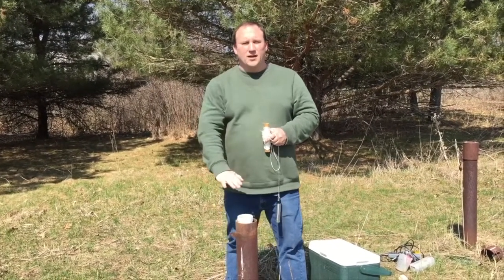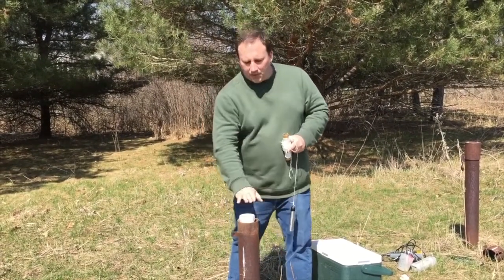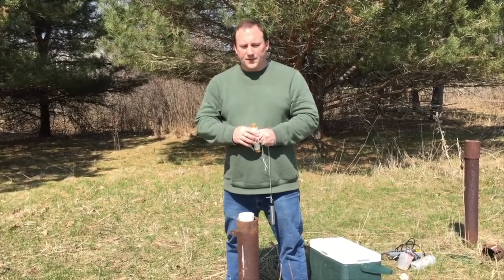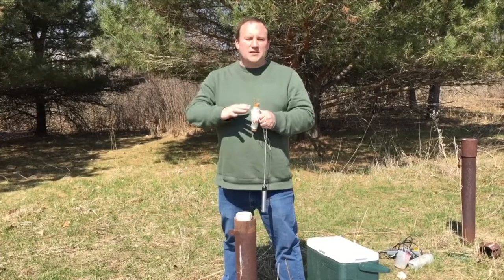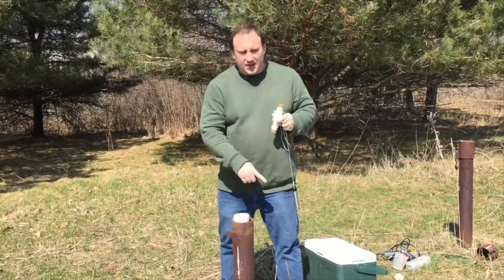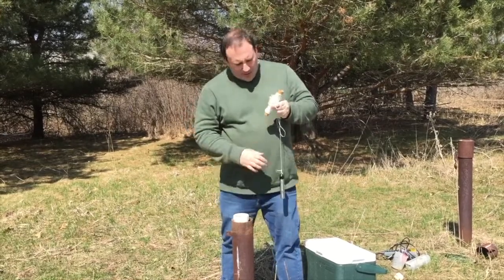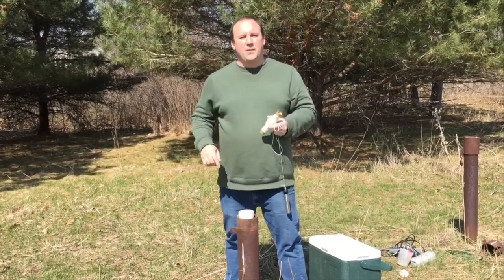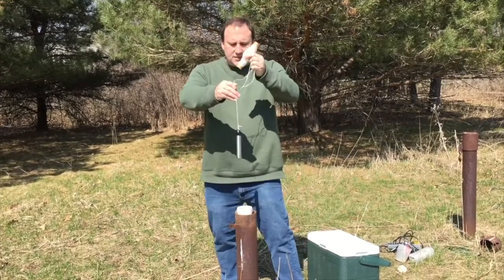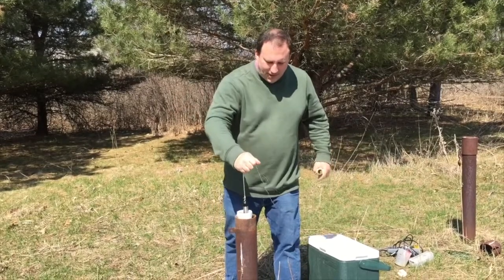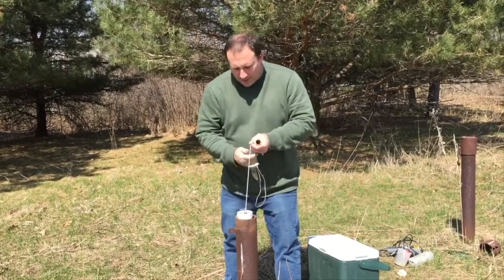The bottom of this well is 45 feet below top of casing, or about 42 feet or so below ground surface. So there's plenty of distance between where this data logger is going to be hanging in the well and where my slug is going to be moving in and out. And if I have a nice smooth rope like this, there shouldn't be any way that it's going to be hung up on that. And everything should be good. This is heavy enough. So I don't have it fully connected to this string, so I'm going to be extra careful while lowering this into the well here.